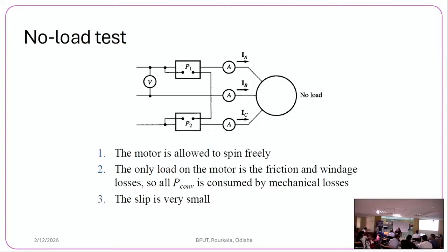Effective area is only considering the outer surface. So because area of cross section decreases, the resistance becomes higher. It is R equal to rho L by A, resistivity into length of conductor divided by area of cross section of the conductor. When the frequency is higher, the effective area of cross section of the conductor reduces, so resistance increases. So AC resistance is higher than the DC resistance.